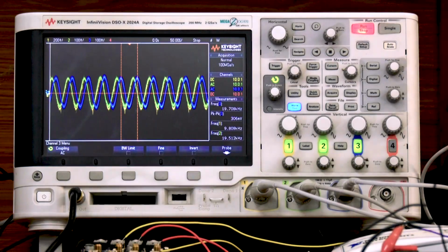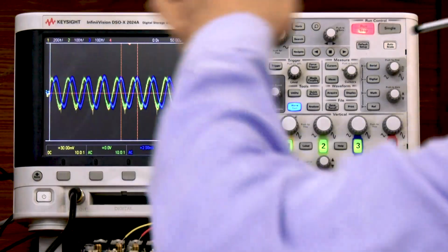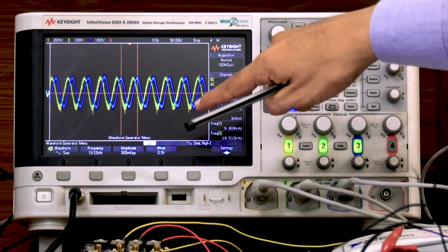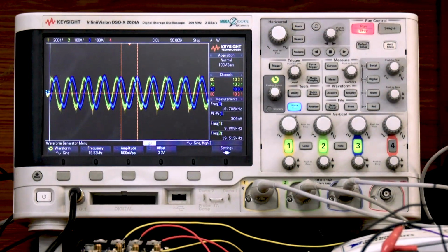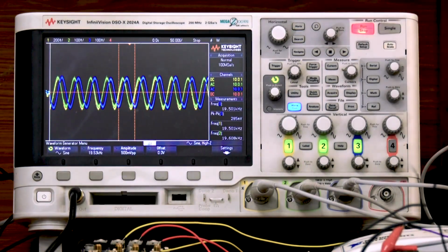So the input signal we were giving is a 19.53 kilohertz signal, which is shown here, wave chain. So a 19.53 kilohertz signal was given, and we are able to extract the in phase and quadrature phase of the input signal. So in this session, I have shown how basic programming can be done in the Altera based environment, basically on the DSP Builder, and I have also shown you two programs. One is a basic ADC DAC program, in which any signal can be given from the outer environment to the ADC, and it can be taken through the DAC and shown on the DSO.